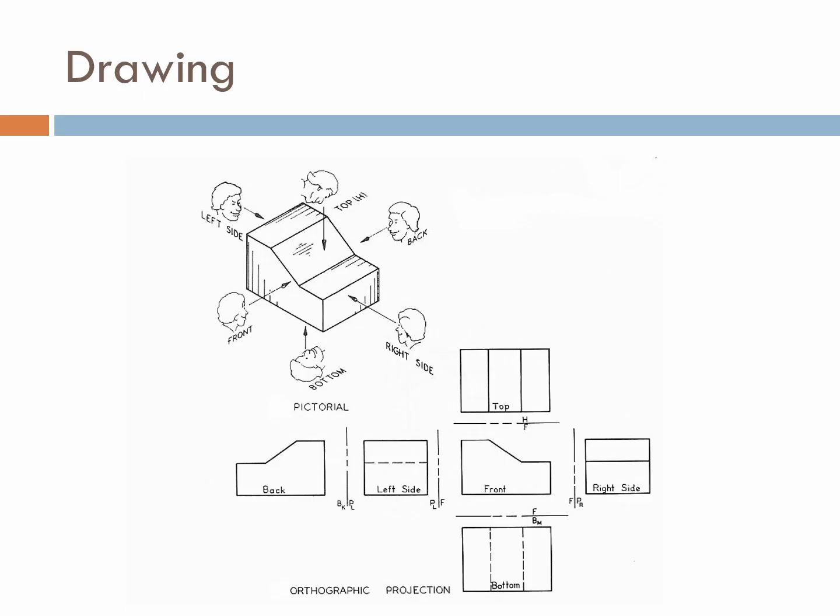Here again, front, top, bottom, right side, left side, and if you had to see something in back, it's on the other side of the left side. See front here, right side, and top. So really, it's not hard, but you have to keep in mind, a lot of people get in trouble when they try to draw. They know there's something else going on, so they try to draw it in there, even though you can't see it from that particular side. Okay?